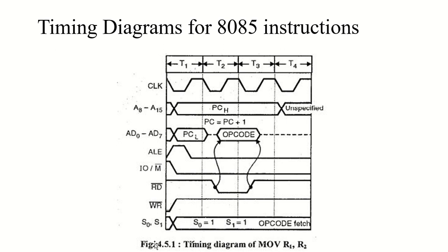So again, I'm repeating one more time. For this cycle, the address is given by program counter, and program counter is incremented by 1 to point to whatever next instruction. Now can anyone tell me, does this instruction require T5 and T6 stages? Will there be any changes if we draw the T5 and T6 states? Right, there will be no changes at all. So we don't need T5 and T6 stages. So the timing diagram will be limited to this only, just one opcode fetch.